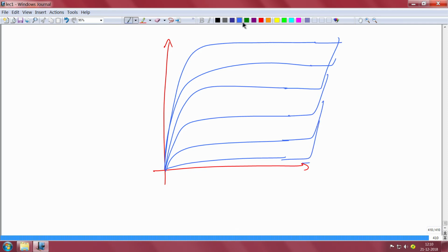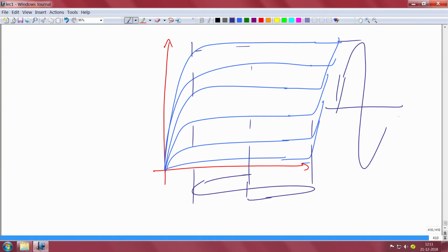Okay. So, to get maximum power, you would want to bias at the middle of this, so that you get the maximum swing here, you get the maximum power, and so you are biasing at some midpoint here, right. Because that is why you are able to get both the swings on middle of middle, right.